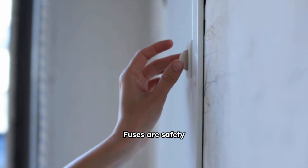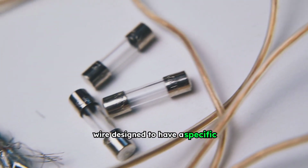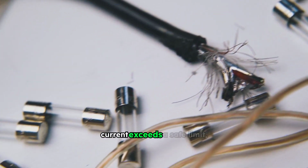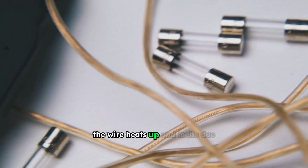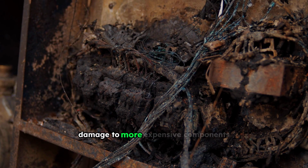Fuses are safety devices that use resistance to protect circuits from overcurrents. A fuse contains a thin wire designed to have a specific resistance. If the current exceeds a safe limit, the wire heats up and melts due to its resistance, breaking the circuit and preventing damage to more expensive components or fire hazards.